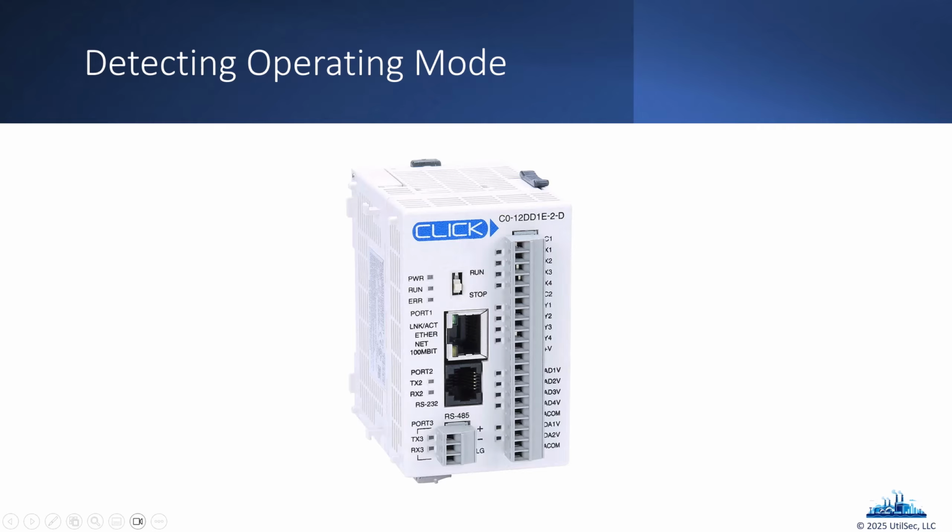That's it. So either the PLC is running and doing what it needs to be doing, or you've stopped it for programming. So that's when you can put a new version of firmware. You can make PLC logic changes. Now, if it's in run mode, you can't change the firmware, but you can change the PLC programming.